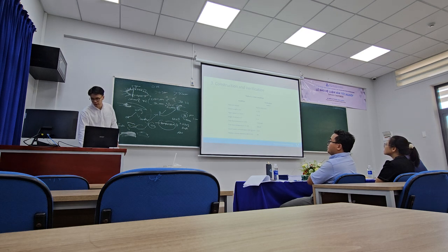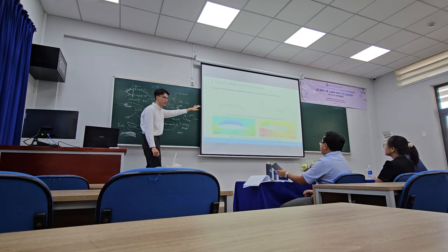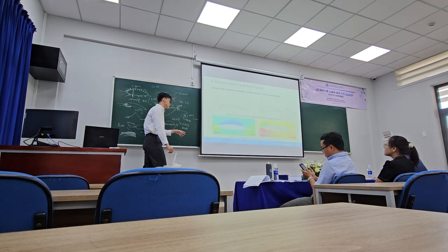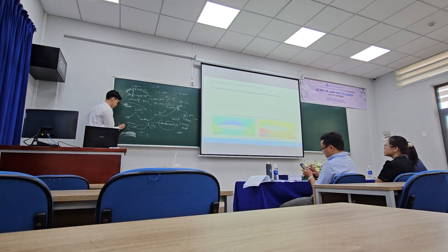As you can see, the validation doesn't show many differences, because NASA used the Lagrangian method, which calculates droplets one by one, and this needs more resources to calculate. So I chose Eulerian, but we have the same result as the Lagrangian.